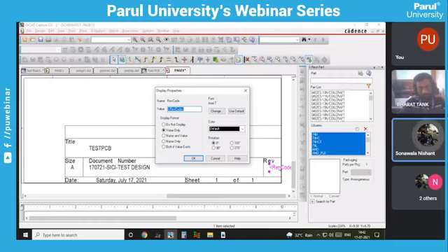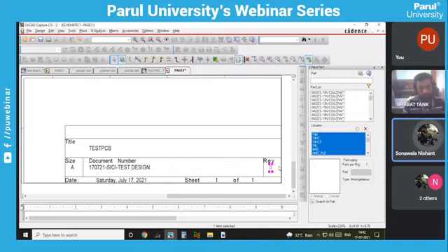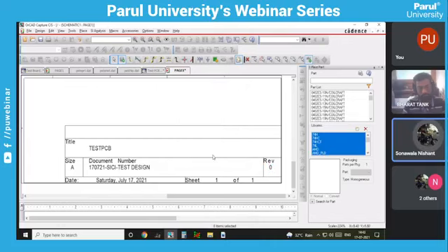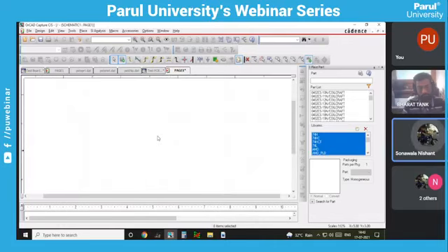When you design a schematic, you have to start with revision code 0. Why? Because you have no idea what changes will be made after you create it. So when you create your schematic and changes come in, then you have to maintain your revision like 1, 2, 3, 4, 5, 6, so that you can identify how many times you have updated your schematic. So we'll start with 0. Now let's start with the designing.